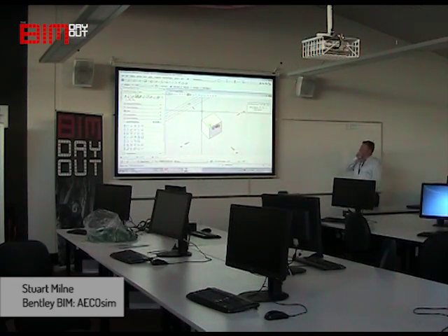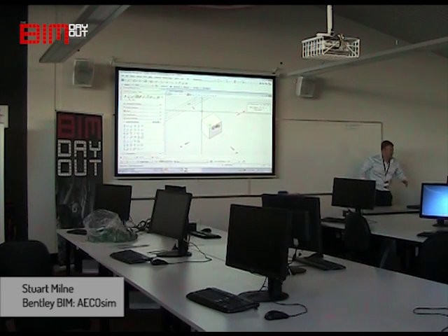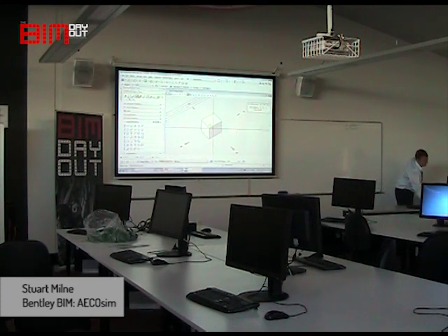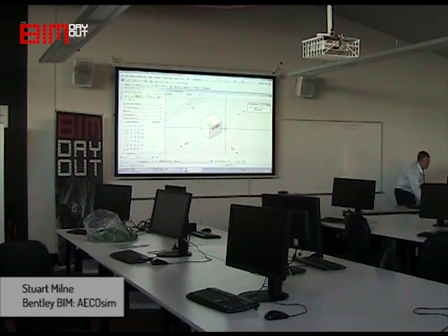Now, with the window area, you have this little toggle switch that says move camera. What that actually means is, if that is unchecked and I zoom into something, my zoom angle changes. So I'm just zooming in and out. If I check this box and zoom in, rather than changing the angle of my focus, I'm actually physically moving myself. So you go to that window area and just check the move camera box. And you can draw a window to zoom into different places.